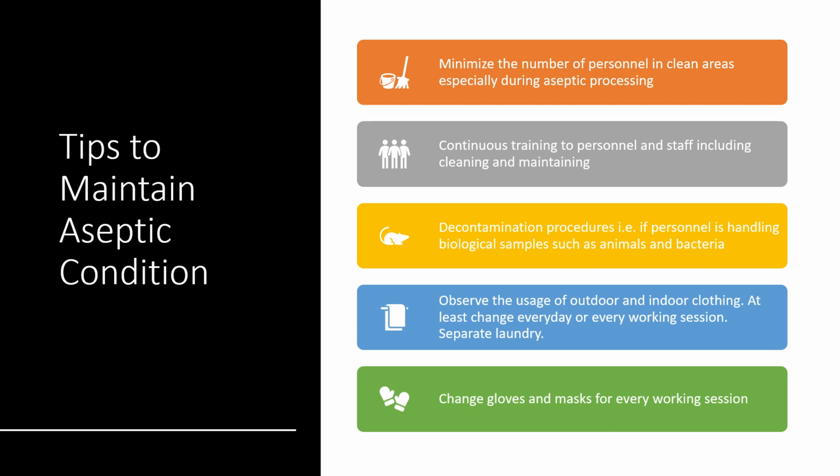Observing the usage of outdoor and indoor clothing is also crucial. Personnel should change their clothing regularly, at least daily or before each working session, to prevent the introduction of contaminants from external environments. Additionally, maintaining separate laundry facilities for cleanroom garments further reduces the risk of cross-contamination.